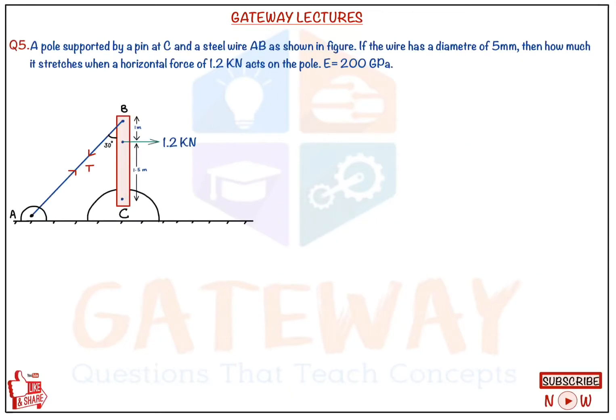A pole supported by a pin at C. So there is a pin, nothing but a hinge at point C, and BC is a pole, and a steel wire AB is as shown in the figure. So it is supported by a steel wire AB. If the wire has a diameter of 5 mm, then how much does it stretch when a horizontal force of 1.2 kN acts on the pole? So this is actually a basic question.